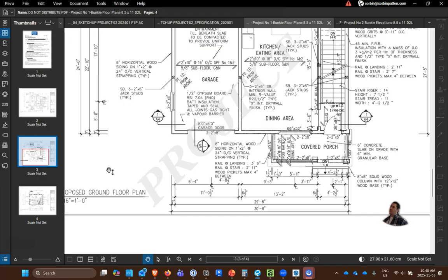The other thing is we don't know the rough opening of the door. So a window company may have a 1/4 inch or 3/4 inch rough opening. They may have a 1 inch rough opening. And so when we say the center of the door, the contractor doesn't have to artificially move the dimensions every time. We're just always kind of forcing them to do math, which is what it is. But I mean, it's not hard math.